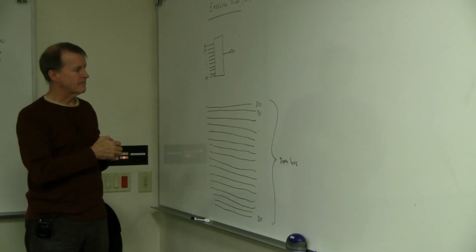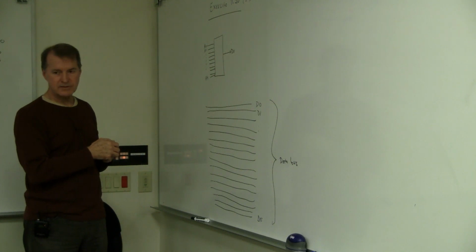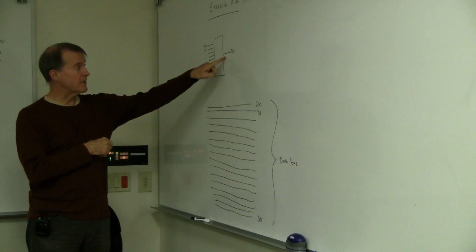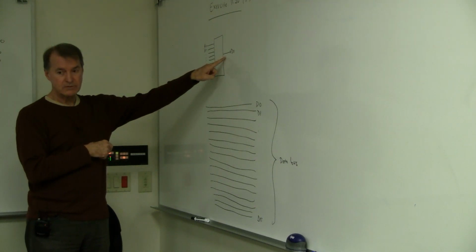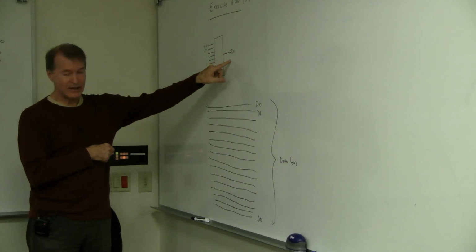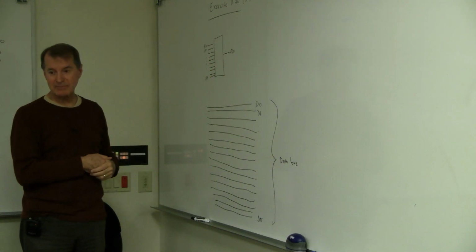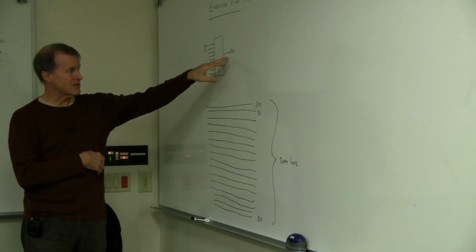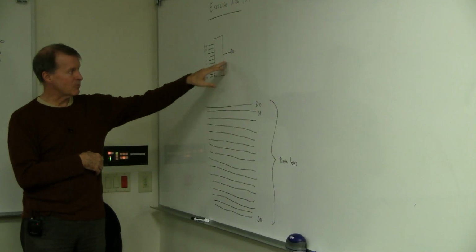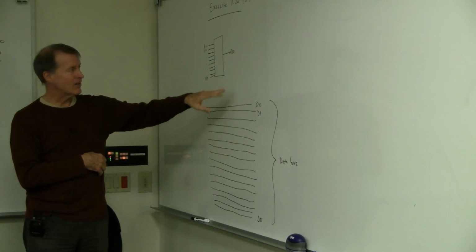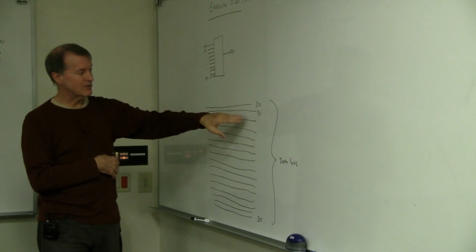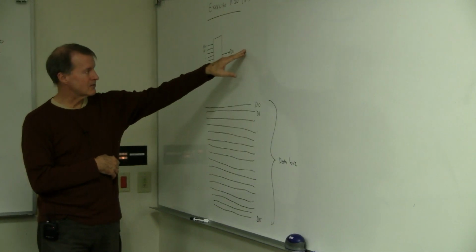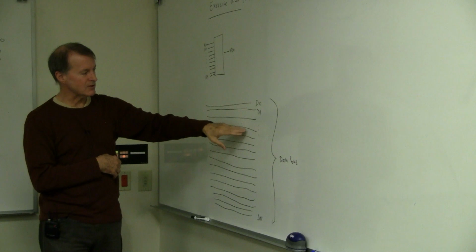Because this is 1024 by 1, that means there's 1024 bits. By 1 means one data out. So what if it was 1024 by 2? Then there would be 2 outputs, and you'd only need 8 of them. How would you hook those up? The D0 of the first would go to D0, and the D1 of the first would go to D1. Then the D0 of the second would go to D2, and the D1 of the second would go to D3.